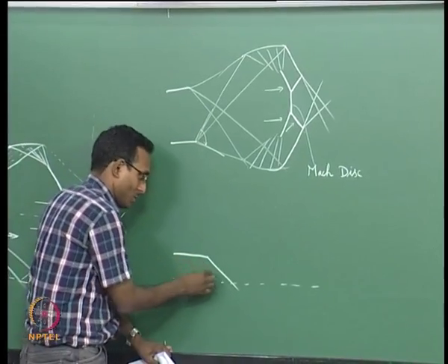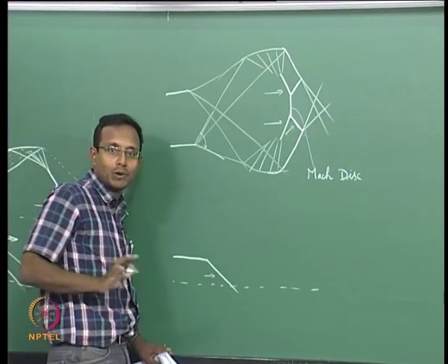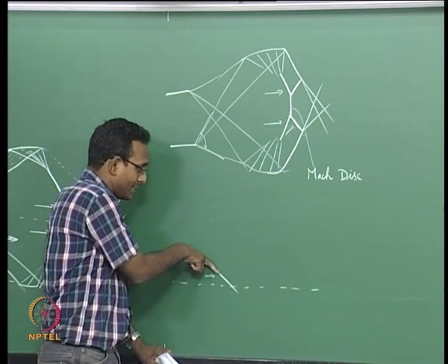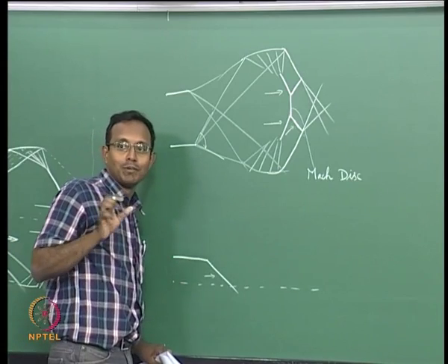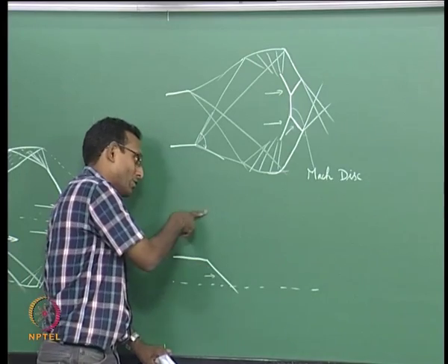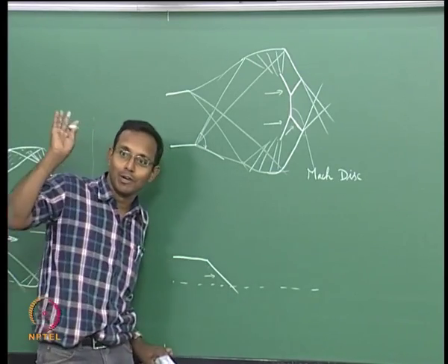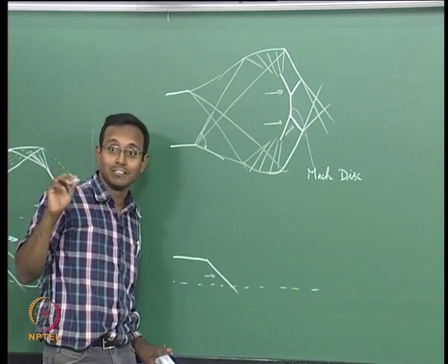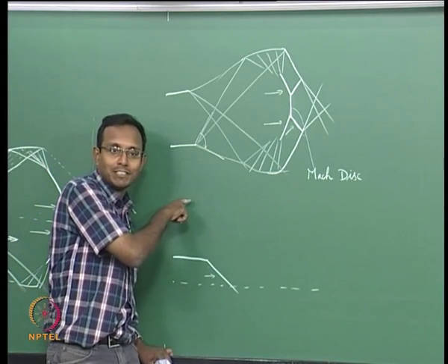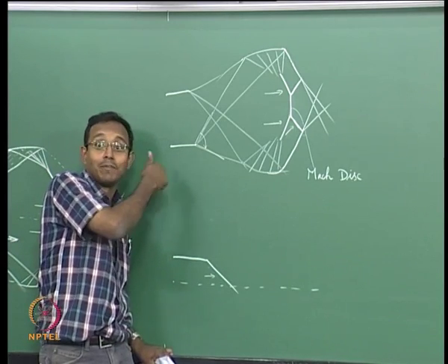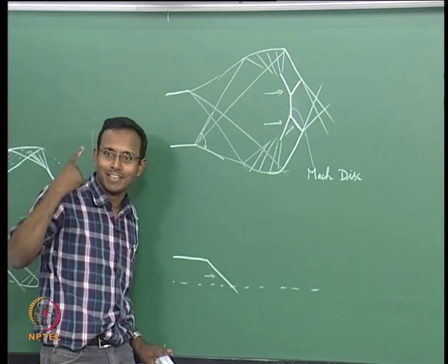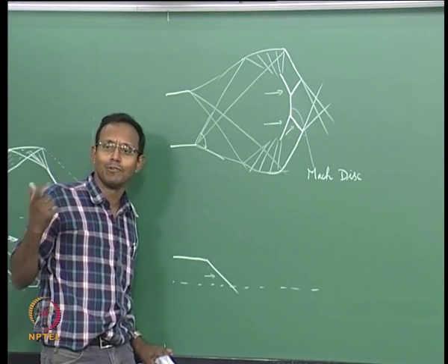Starting will be the same as the original Mach number, Mach angle, that you do not have a choice, but the pressure outside is extremely low, so my delta theta will be very high because my delta nu is going to be pretty high. We know, if it is Mach 1.5 here and I have very low pressure here, then I know I can have all the way up to around 120, 130 degrees turn, right. We said if it is Mach 1, then 130 degrees is the best turning angle you can get for infinite Mach number expansion, right. Pressure should be 0 for that, which is not really possible. We also said that when we were dealing with Prandtl-Meyer flow long back.